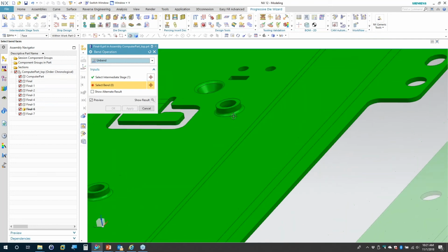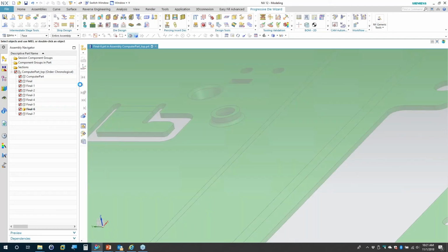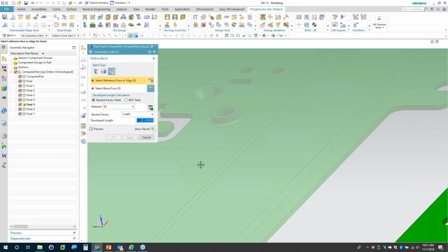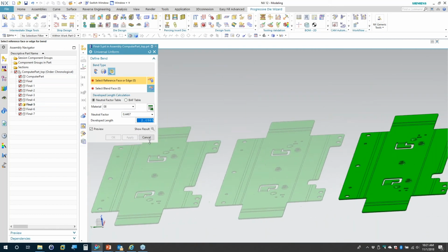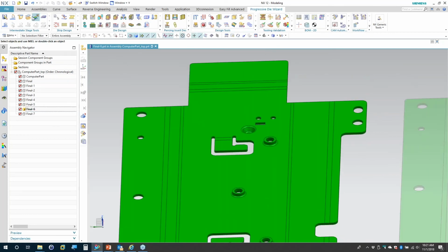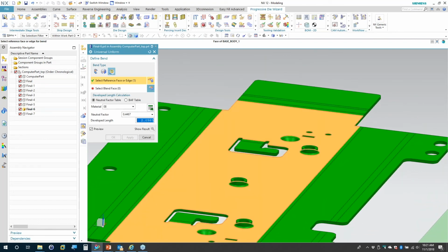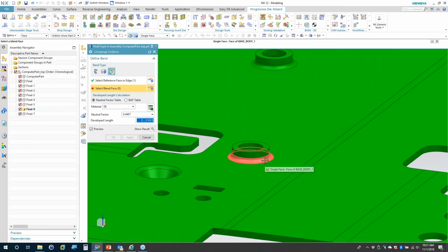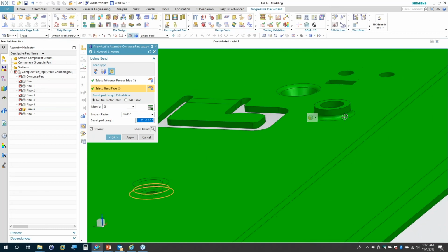Now we've got some circular bends here. So the bend operation here is mainly for straight break. We have other advanced tools that we call unforming. So there's a universal unforming tool that's available for basically flattening or unforming individual curve bends. So whoops, I forgot to activate that stage. So let's go down here and from the base face, the center face of the part, we can select some of these circular faces and essentially unform them back into the flat shape. So you see how it kind of pushes down in there again. And we'll do that for all 3 of these at once.